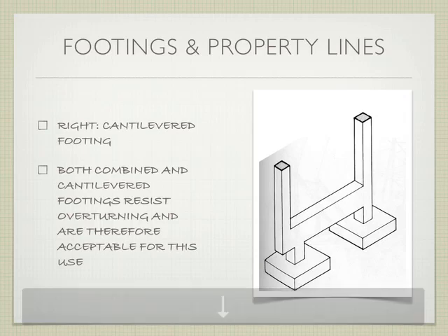The other option that I have is called a cantilevered footing, right? Similar concept, but it's where I have the footing down below, I have a column coming up, then I have a beam that runs to the next column and footing, which can then support the weight from up above. That make sense? This is way more costly to build, right? So we increase the cost every time we do something like this, right?